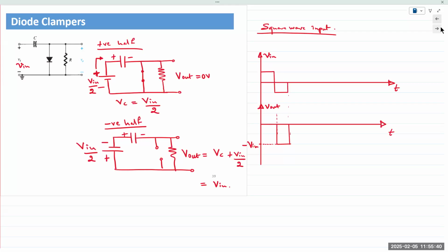So oftentimes it happens, especially when we use amplifier circuits, your amplifier circuit will insert a DC component to your AC signal, either positive or negative. And so in this case we want to remove it, but in some other cases, we might want to add it in. So in either case, we'd want to either add or remove a DC component from our output signal.